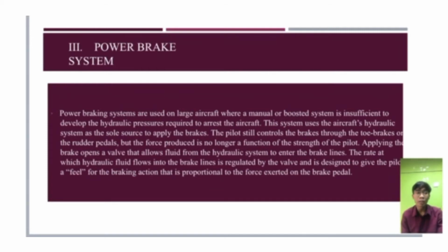Applying the brake opens a valve that allows fluid from the hydraulic system to enter the brake lines. The rate at which hydraulic fluid flows into the brake lines is regulated by the valve and is designed to give the pilot a feel for braking action that is proportional to the force exerted on the brake pedal.